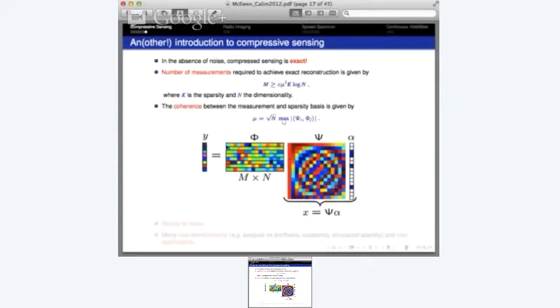If it just contributed to one element in y, then we'd have no way of recovering this full vector from just a small number of terms in y. And that's exactly what the coherence is saying. If we take one element here that pulls out one particular vector, we want that to be spread. We don't want it to be represented efficiently in just one sensing basis vector. We want it to be represented in all of them. That's why the coherence is really driving the reconstruction quality.